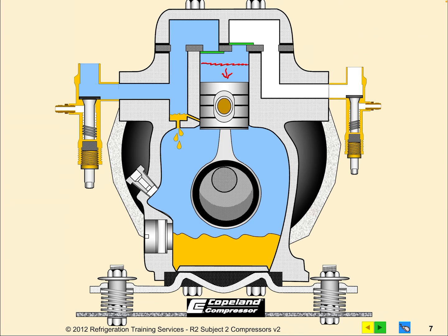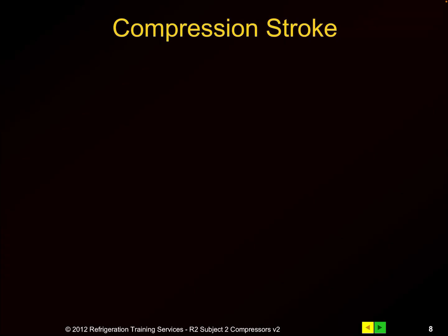As the piston moved down, we made the space bigger with the same volume in there, and of course that allowed the pressure to decrease. When it decreased, that allowed the valve to open up and let new refrigerant come in. That's really what has to happen to get it to flow. So that's the first part that's got to happen.